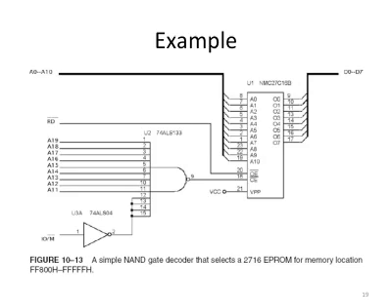Here we have a memory chip. This is an EEPROM 2716. It has 11 address bits from A0 through A10. It has an 8-bit output. It has an output control, chip select, and then power.